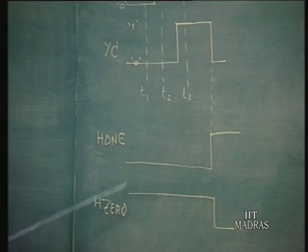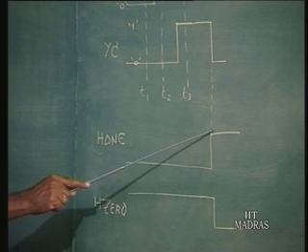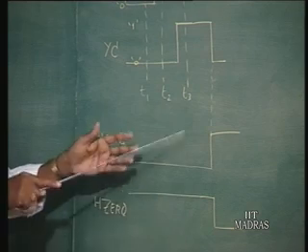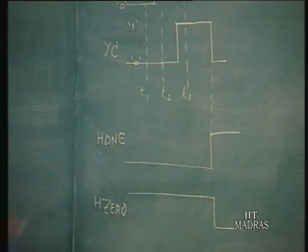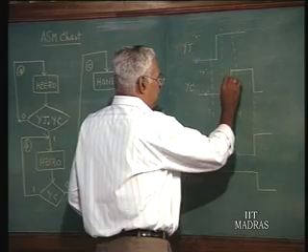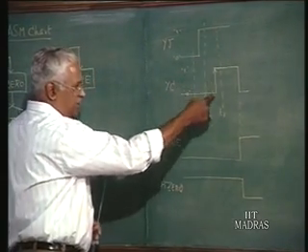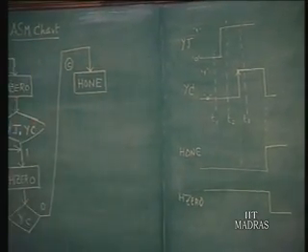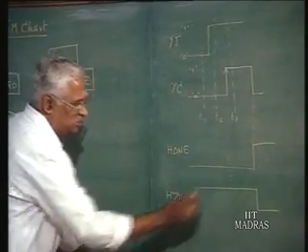Now, pay some attention to this because we are talking about H1, H0, and we are also talking about level 1, level 0. Basically, it is nothing but the complement of the other one. 0 is the complement of 1, and so here also you will find the waveforms as complements. Now, I said during this transition edge, the input is sensed. So, internally at this instant itself, there was a change in the state, but as far as the output is concerned, no change.